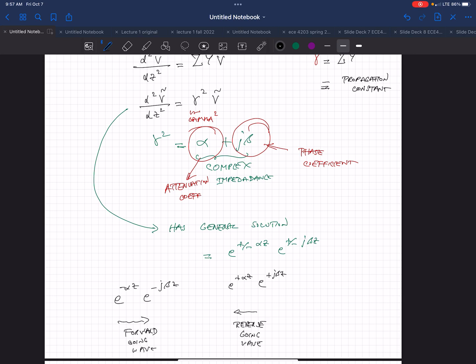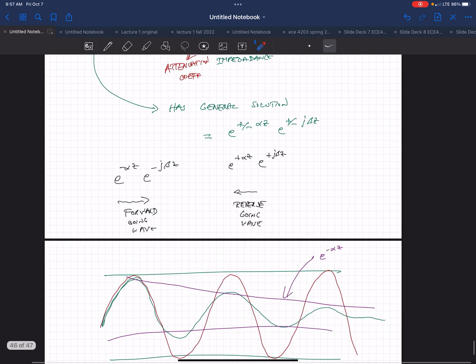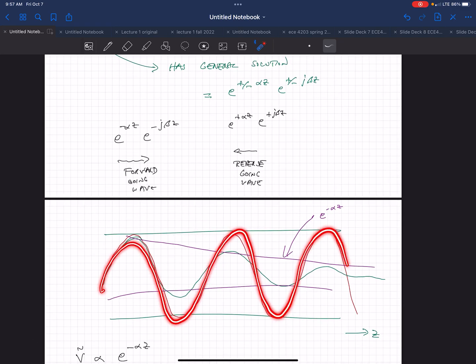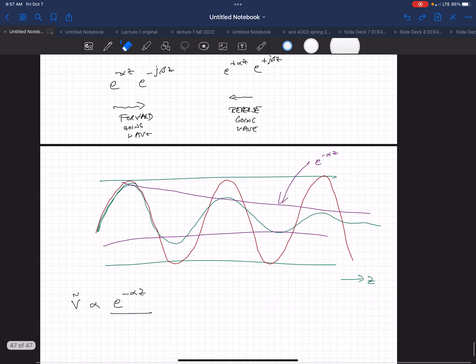No, we still don't have the imaginary part, so why is the phase not changing? Sorry, what I meant to say is the phase is changing going through the transmission line, but our equation for how the phase changes is the same whether you have a lossy or lossless transmission line. So the fact that we threw in resistors doesn't affect how the phase changes as you go through the transmission line, but it does affect how the amplitude changes.